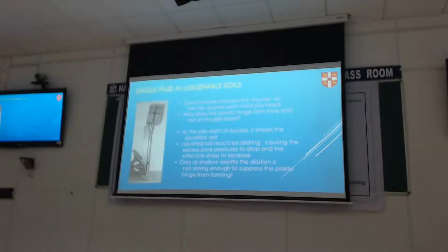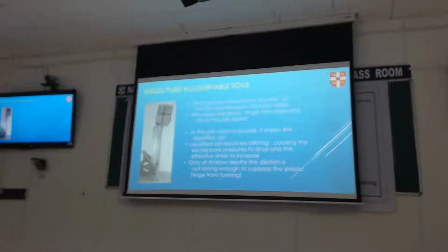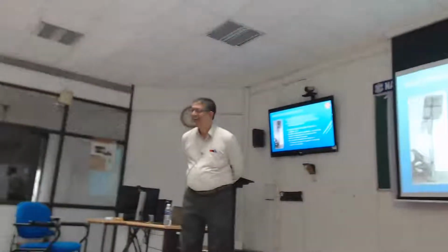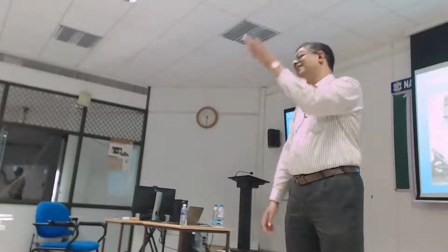When I drive piles in the site, it's hardly straight. It is always imperfect. So how do you account for imperfections in the pile design process? Absolutely. One of the things I was looking at was that people all know pile wander is a thing, and you can get the base of the pile to be maybe several feet away from the initial alignment.